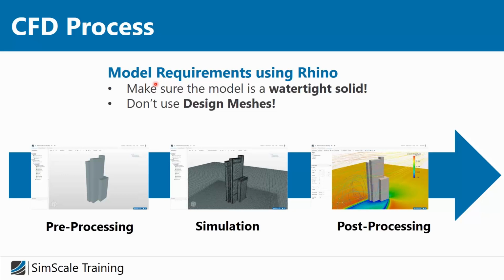And now we will set up an external aerodynamic simulation of this skyscraper design. And basically we have 3 steps. The first step is that we will import the CAD model, the Rhino model, which we have prepared before, and generate what I call elements. This process of replacing your geometry with a system of small elements is called meshing, because we're creating this kind of mesh structure.